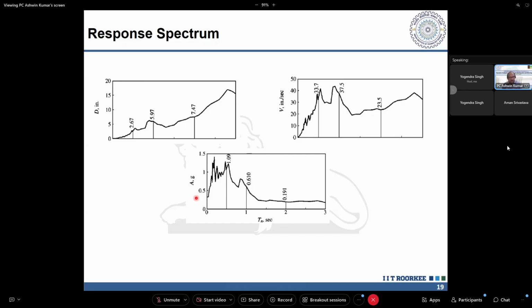Right? Those nitty-gritties I might be missing, like the damping ratio in one, but the whole sentence reads: a linear single degree of freedom system subjected to El Centro ground motion, a single ground motion, the time period is varied, the damping ratio is kept constant, and I'm looking at the peak response. So I get displacement, pseudo velocity, and pseudo acceleration. In our case of structural analysis, where we are looking at buildings and bridges, the damping ratio is almost always less than 20%.